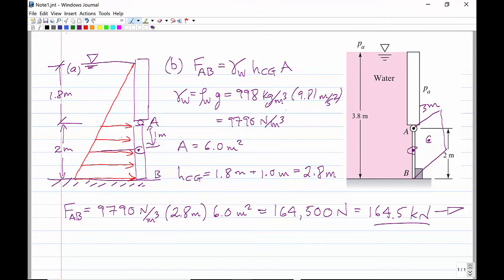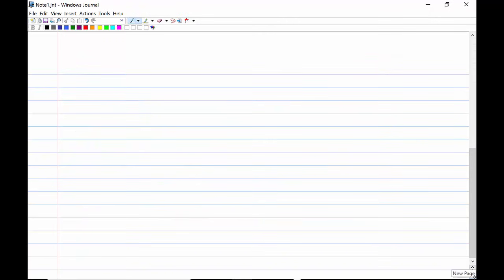We should also, I forgot to point out, make sure when you're drawing these, if you're drawing them on a midterm, that you are careful to show that the pressure vectors are perpendicular to the surface. So the next part of the problem is to find the center of pressure, or the line of action. It always acts below the center of area. We need to find out what that distance is. Let me go to the next page. Okay, and I'm just going to take a second to draw this gate in 3D.